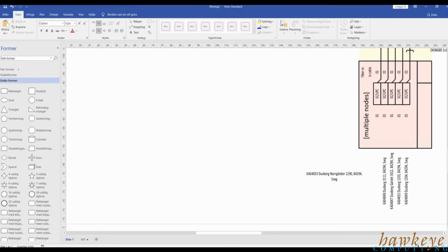If we would have wanted, we could have generated a detailed splice plan for the complete panel, even though it is usually better to focus on certain sockets of interest to improve the readability. But just to show you the capability of the system, let's generate a detailed splice plan for all the sockets in the panel.